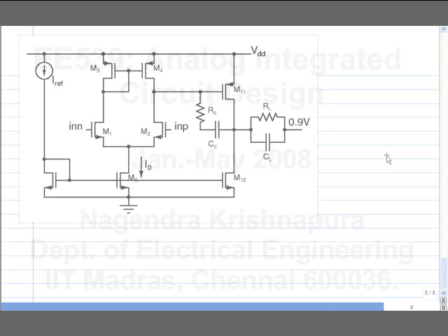Current through M12? Okay, because we are out of time, we will work it out quickly. Let's say that, first of all, let's neglect RL. Generally it's only capacitive stuff that matters for slew rate, so let's neglect RL completely.